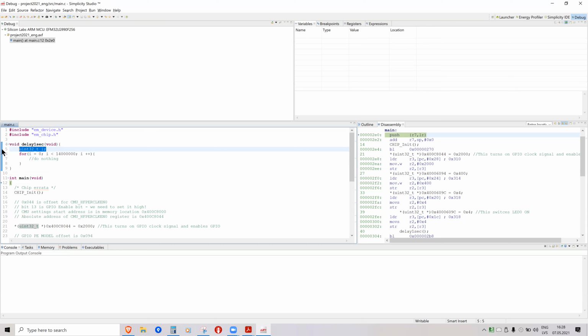This is why you shouldn't put breakpoints in locations where you create variables, because if the variable is optimized out, or if the variable is held in a register instead of external memory and you don't initialize it, this line is only there for the C compiler's information, but the actual action happens, for example, in this for loop. So you add a breakpoint here where something is done with that number. Or maybe you write i equal to 0, then it's an instruction. But if you just create a variable, this is a phantom line, so you don't put breakpoints on those lines.